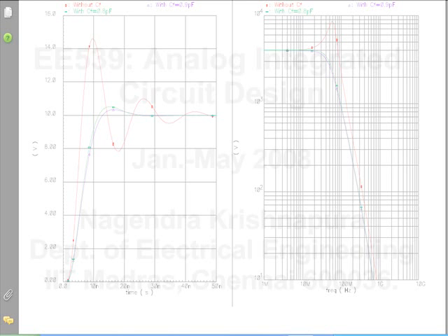So that is if you want a saturating amplifier, but you may not want it, right? Yeah, but it won't saturate, right? I asked for, that's true. If you let the op amp saturate, that was only for modeling, but if you let the op amp saturate, clearly you will not see ringing, but the behavior will be nonlinear, right? So, but also I said that you should adjust the steps so that you get 1 volt output or something, isn't it? Whereas the limiting was 2 volts. So you should not see this. You should not see any limiting at all. Okay.